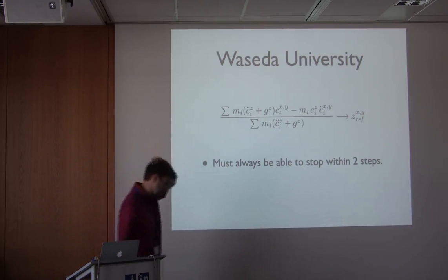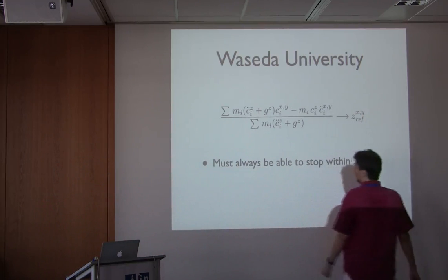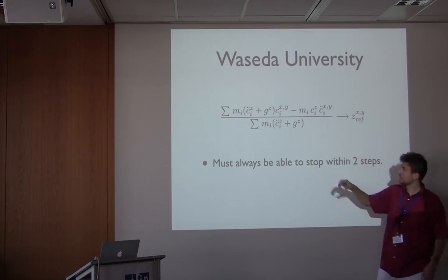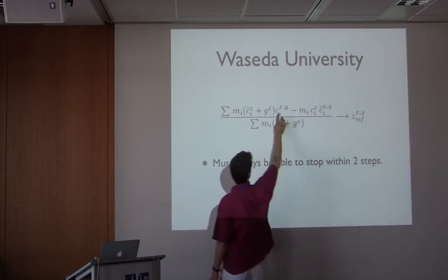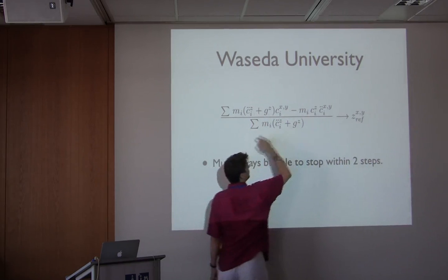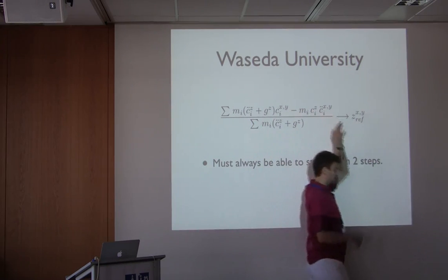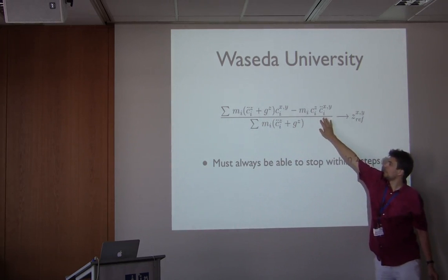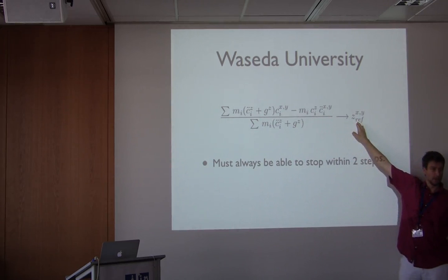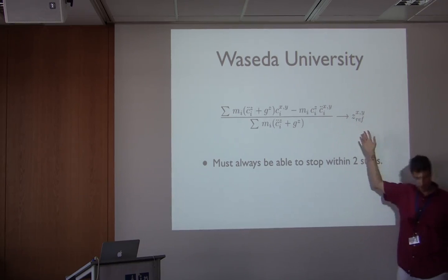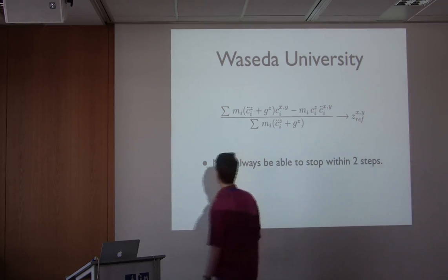Then you have, so historically, it was at a university. What they use is, in fact, a multiple mass model. They consider multiple mass, but here you have the same equation for multiple mass. You have the position of the center of mass, the acceleration, multiplied by the vertical acceleration, vertical position. Then you have an iterative process to make this value converge to a predefined center of pressure. Okay, so you have a trajectory for a center of pressure, and then you solve this equation to find a motion which will satisfy the dynamics.